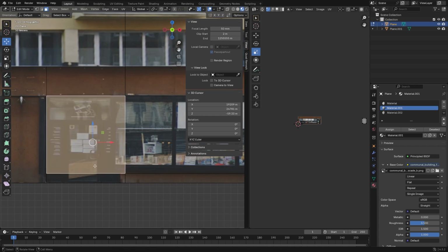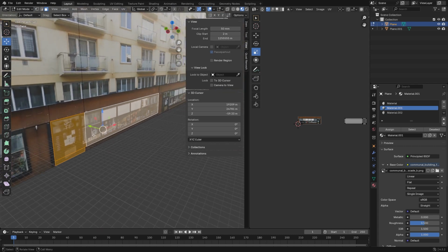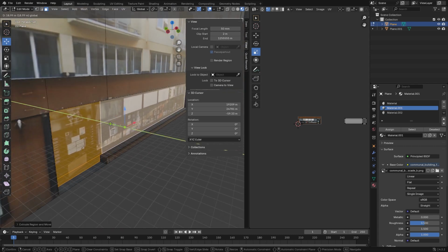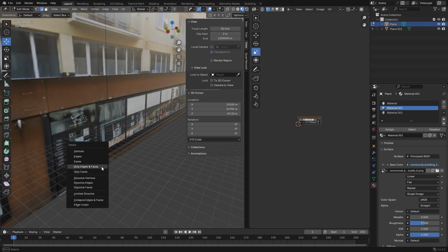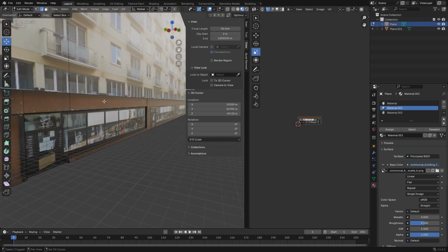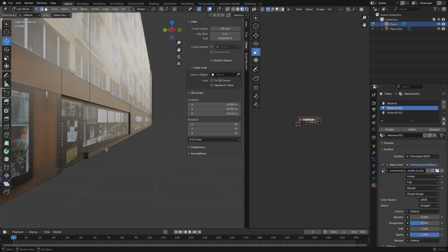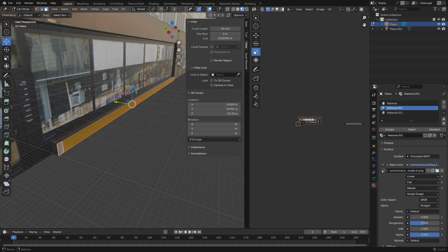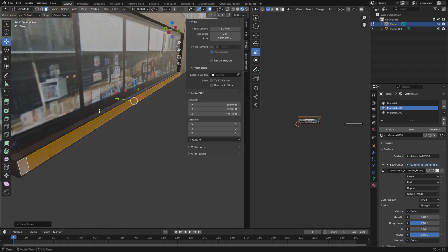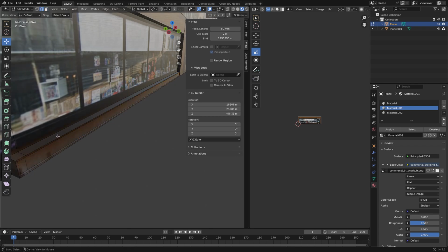Select the faces and extrude them backwards. Let's improvise a bit with the tools in the edit mode. You can select multiple edges while holding Alt when selecting.